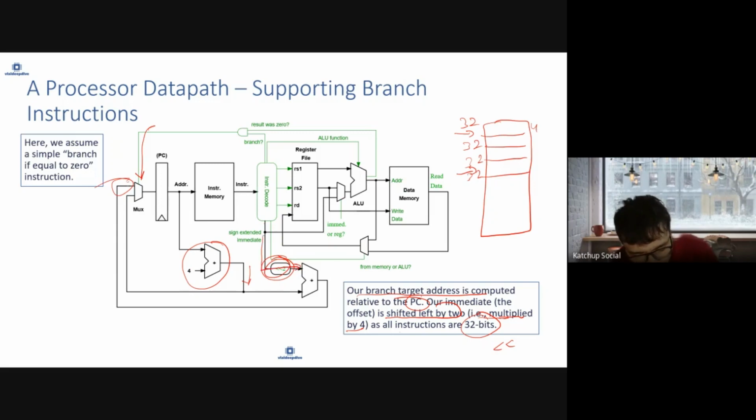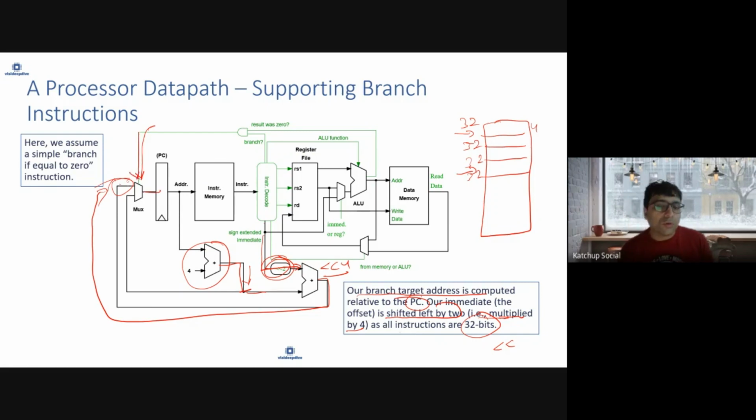So we'll jump to the next instruction level by multiplying by 4, and this can be enabled like this. For your program counter, if you want to branch, rather than addition of 4, you multiply by 4, which is this 2 left shift operator that you provide here. So now you can go to the next instruction or jump. We are fixing a fixed jump here, so you multiply by 4, and that gives us a fixed jump where you can increase your program counter. This is how you can also do a branch or jump kind of instruction. We had earlier just added a mux here. Now we have connected this mux to a multiply by 4 operator, and then do this branch operation.